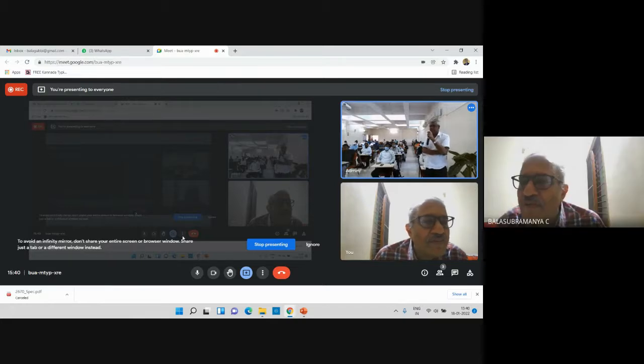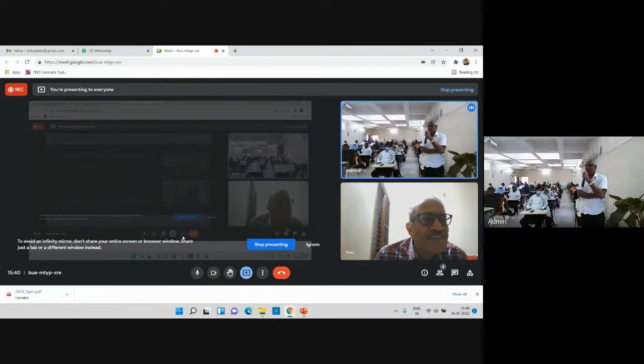The second question is about the PLC metering, where the predefined meter communication interval is around 15 minutes. We have predefined communication from the meter to the head-end system. But I find that most of the time the communication from the meter to the system fails. So we don't have real-time data from the meter to the system, and thereby we are losing the accuracy of the metering.